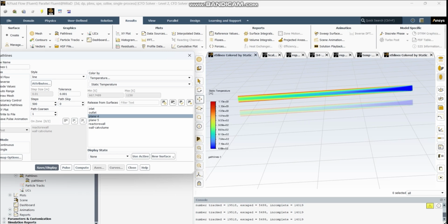This thermal distribution also affects the selectivity and conversions in your reactor. The initial high temperature helps achieve rapid methane conversion, while the gradual cooling favors the water-gas shift reaction, which is favorable at low temperatures. Therefore, this distribution, while not uniform, may support a two-stage strategy: high temperature for reforming, and a low temperature to maximize the hydrogen via the shift reaction.